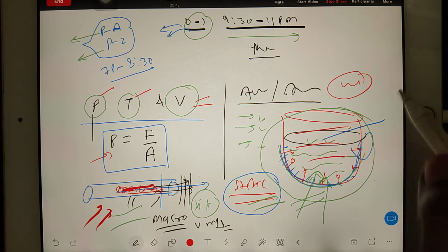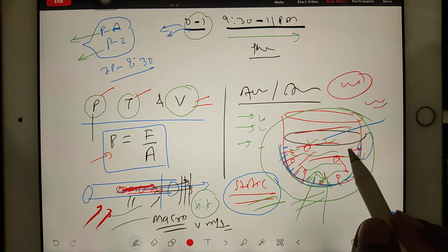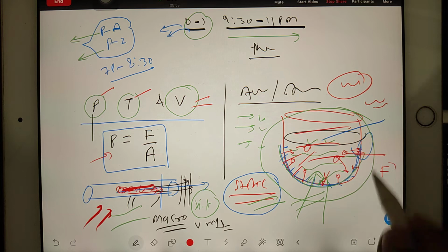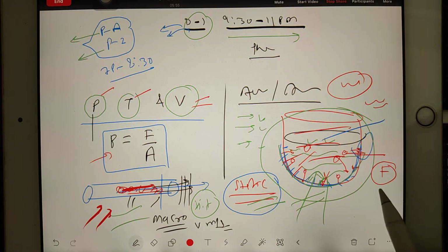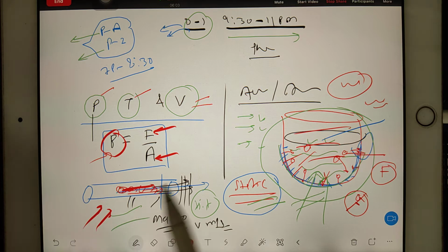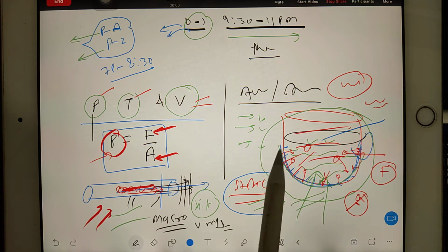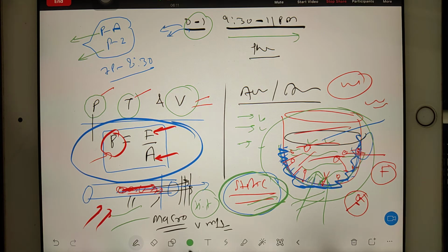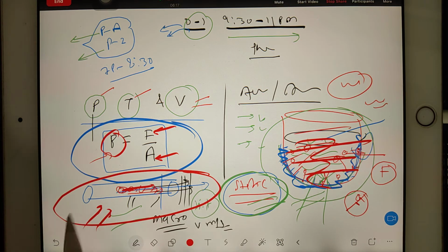With your naked eyes you can't see the movement of the molecules, but in reality molecules are not at rest, they are moving. Because they are moving, they are bombarding the wall. Because they are bombarding, they are applying some small amount of force. Because the force is there, the molecules touch a particular area, so area is also there. There we define force and area, and then we define static pressure. When all the molecular bombardment is accounted together, that pressure is your static pressure. Why is the name static? Because the entire fluid is at rest. But in the case of a pipe, flow is there, all the fluid is in motion.